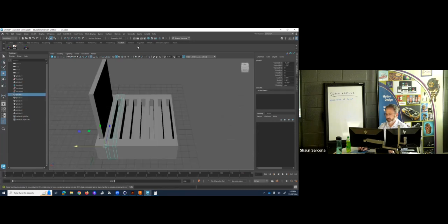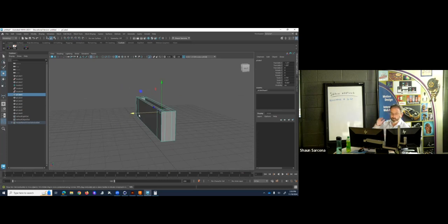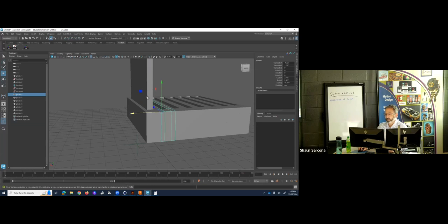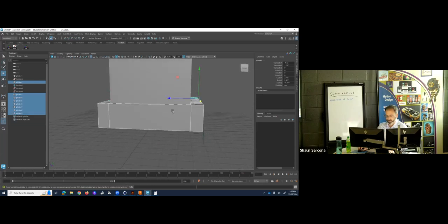Now these, I isolate it. They have their faces on both sides. I can't have that. This has to be one solid piece. That's the only way that it's going to print. If I were to send this to print, it would actually print 8 individual pieces right next to each other. Don't want that. So I need to go through and delete all of the faces that are on the inside.